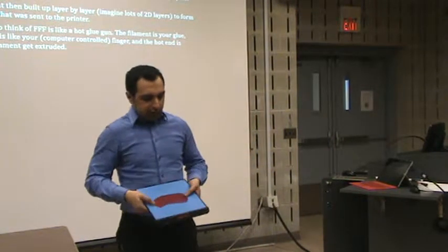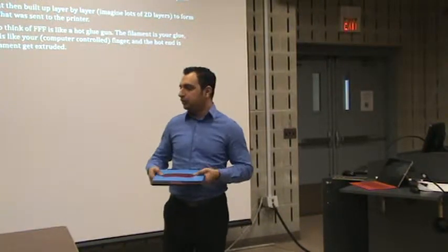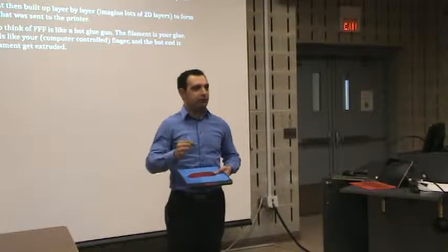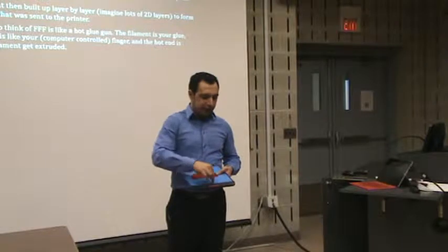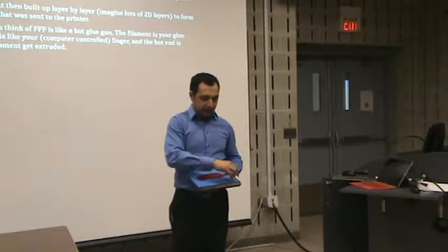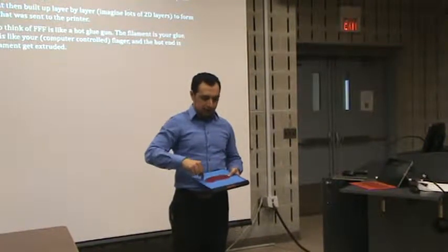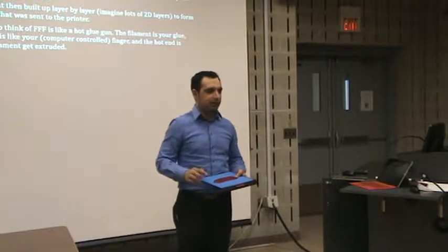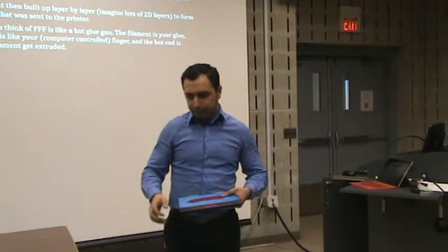So there are two ways to make sure that your model is very well printed. First thing is to make sure the extruder extrudes uniformly. So what MakerBot does is, whenever you give it a command to print, it will just print a straight line here to show you that the extrusion is working fine. Okay, it will print a straight line here. Then some people, usually I try to do that, is to try to build a small skirting around the model so as to know that it's working fine. And a raft is absolutely essential, and basically you can scrape it off.